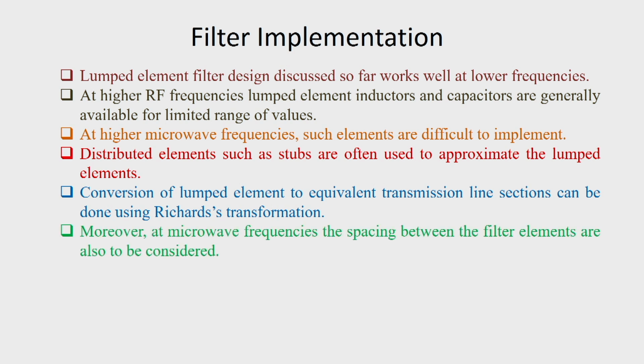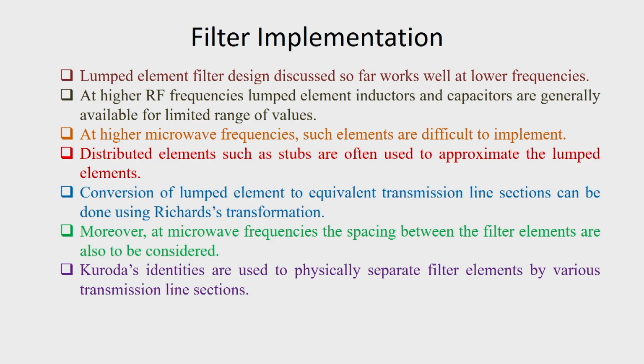Moreover, when we connect these elements in a microwave circuit, the spacing between the filter elements are also to be considered at the microwave frequencies, and Kuroda's identities are used to physically separate filter elements by various transmission line sections.